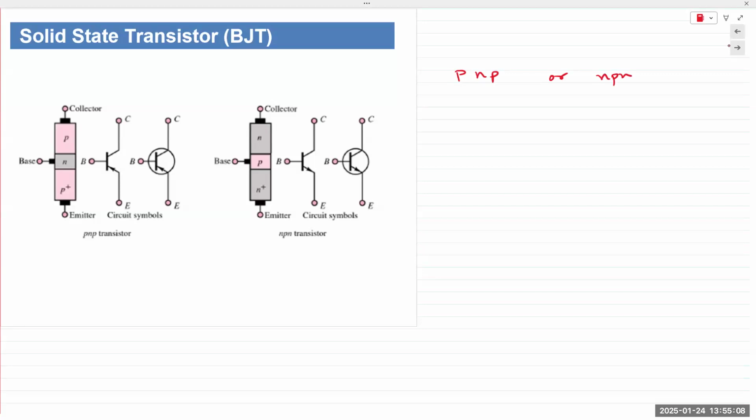Okay, electrons have higher mobility than holes, almost 3 times as much. So NPN transistors are, by their very nature, faster than PNP transistors. That is not to say that we cannot create similar speed devices. But if we keep the exact same doping levels and the exact same design, then NPN transistors will be faster than PNP.